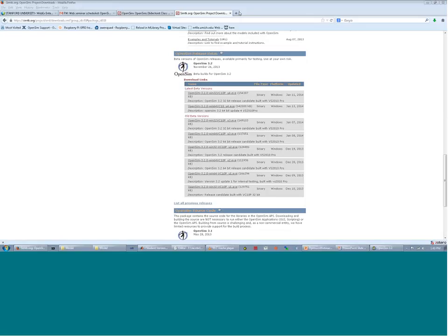And it's much easier, as you saw in the GUI, to change those mass and inertia parameters of the model. What you can do is change the contact mesh of the foot. If I wanted to go from a cylinder with radius, say, 50 millimeters to 100 millimeters, I would need to make a new file and import that instead of the one that's in there. So I would say if you're going to use curved feet or some other element, design those first and then adjust the model parameters in the GUI later. That's probably the easiest way to get started.